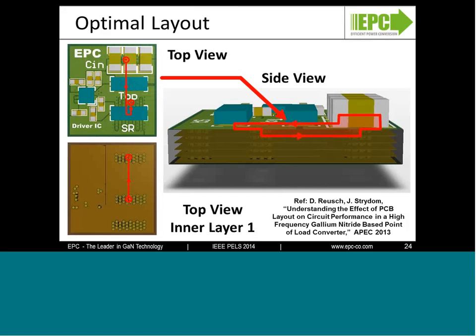If you want to look further into more details of how we achieve this design and how it improves over conventional designs, you can see our paper that's referenced here. But the idea with this is that we have an ultra-low profile self-canceling loop, and we can achieve total parasitic inductances, including input capacitance, the devices, as well as the PC board, under 400 picohenry. And that's significantly lower than even the best state-of-the-art trench MOSFET module, as we'll show in the next slide.